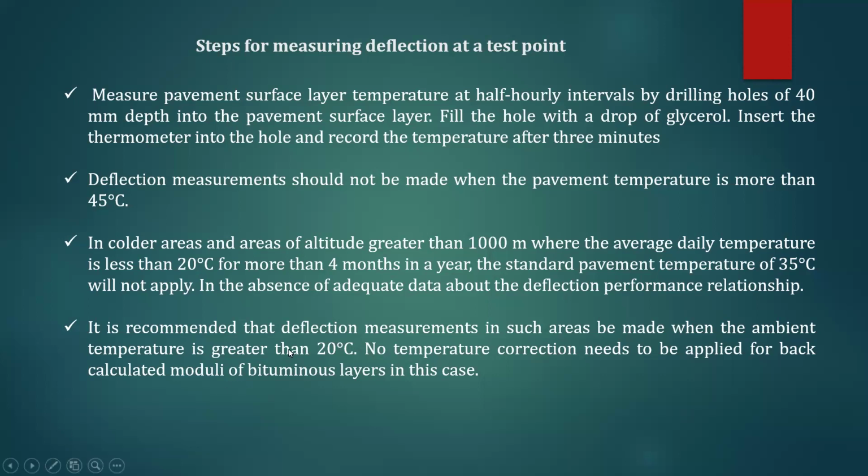It is recommended that in colder locations, deflections in such areas will be made with an ambient temperature greater than 20 degrees centigrade. So there is no need to apply the temperature correction for the modulus of the bituminous layer in this case.